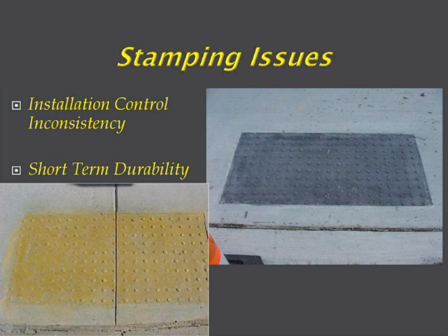You all being concrete contractors, you know that the weakest part of concrete is at the very top where you just have the paste and there's no aggregate interlock, so that's really the weakest part of the concrete. So we found that after maybe one season, you get plows going through and plowing off snow, these things just shred off really easy and wear out pretty quick.